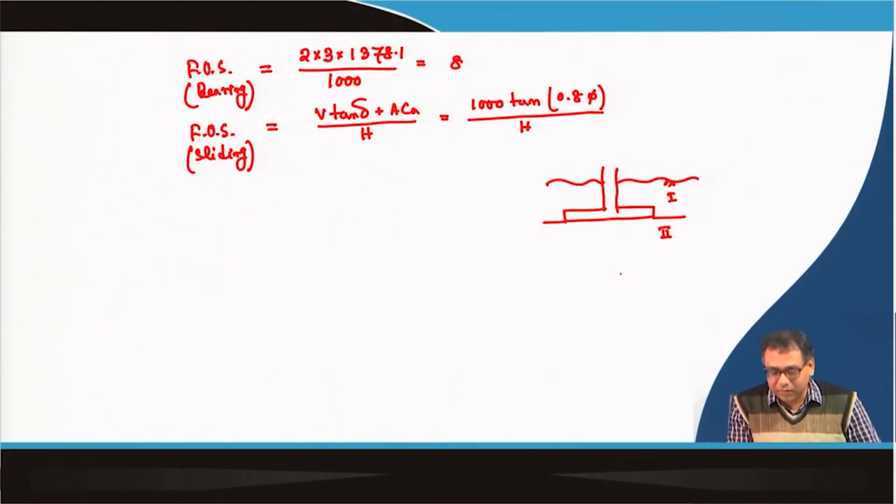So, now when you calculate delta and Ca, do not take the soil properties of layer 1, you take the soil properties of layer 2, because it is the base interaction, where the foundation is resting. Okay. So, these are the properties that you have to consider for delta and Ca. Similarly, for the second term, because there are three terms in bearing capacity, gamma will be gamma 1, and for the third term gamma will be gamma 2, because that is below the base of the foundation.